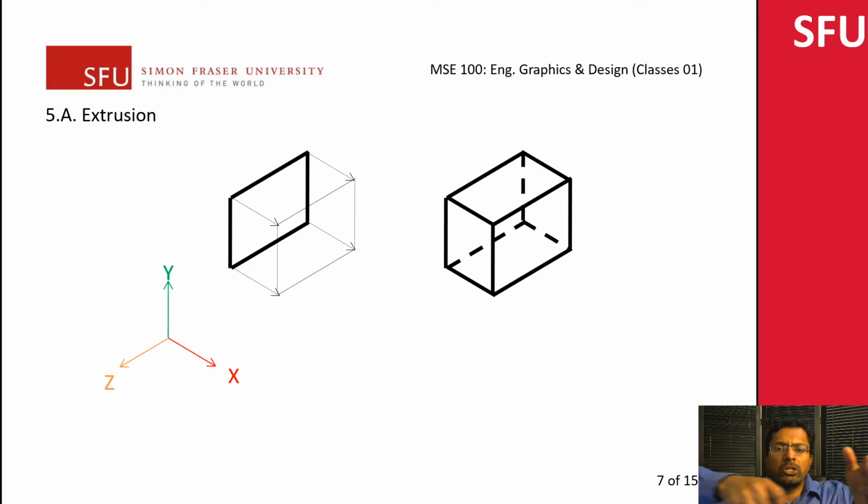So you can essentially extrude the shape to any length that you want, and that's what we do with the extrusion operation in SolidWorks. We take a shape, and imagine we're pulling the shape out of the sheet of paper in the third direction, or we extrude the shape. So if you had the rectangle here in the 3D view, I can just pull it out of the plane, and I'll form this cuboid over here. To illustrate, let's see how this goes.